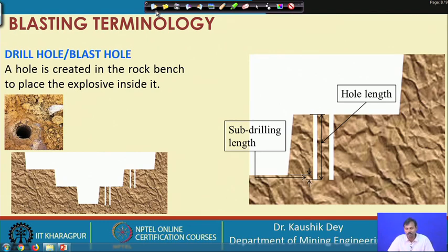You can ask why we need sub drilling. In fact, when we cover the explosive rock interaction, it will be better for you to understand that sub drilling is essential for bench blasting. As we are going for some additional drilling, it is better to get fragmentation of the whole rock mass, so that there will not be any rock portion left at this position.